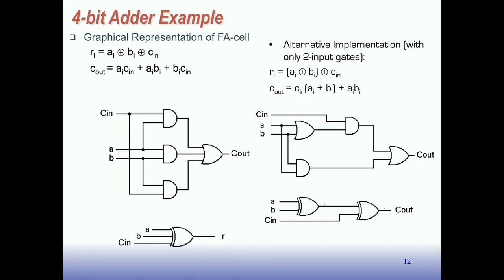Can you always reduce it down? You can always reduce it to 2 levels of logic, but, and we'll talk about this later today, it might get much bigger. If you have common sub-expressions, you can factor those out and then use that multiple places in your circuit. So it introduces more levels, but it might be more compact.